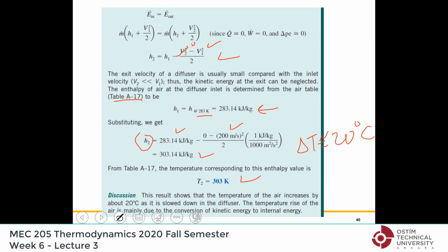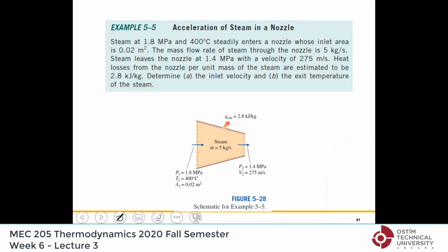So if you look at the energy forms, this equation says that the energy forms involved are enthalpy and kinetic energy. And kinetic energy goes to 0, decreases. Then conservation of energy says enthalpy must increase by the same amount. So this is conservation of energy. So energy is accounted for, and what we are doing here is an accounting of energy.